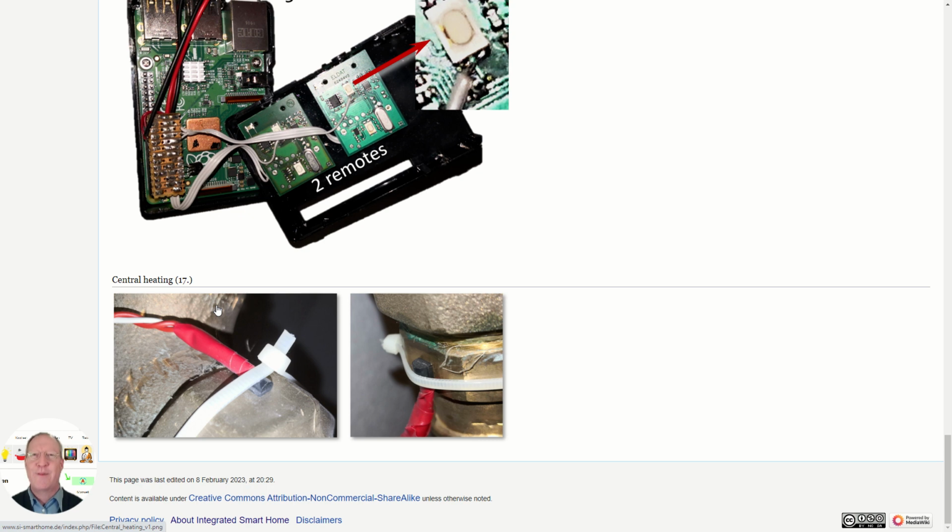The last item I have some photos about is the central heating. There I use one-wire temperature sensors again at different places of the central heating, so I can see the development over time of the temperature. I can define upper and lower limits and can analyze it and send error messages and warnings in case the heating has a malfunction. Usually my experience here is very good.